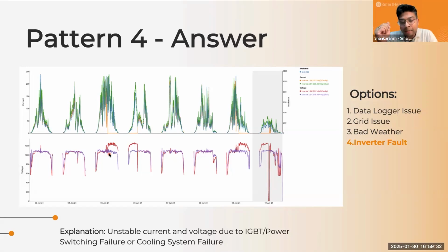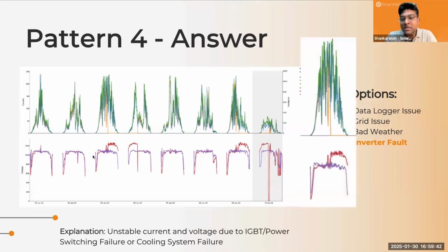It shuts down. A couple of things are extremely important here. First, in bad weather, inverters shutting down could be because of very low irradiance. But if I'm able to build correlations with other inverters having the same configuration, and establish that other inverters are working and this is not, that's the first red flag for me. It's a very common phenomenon for inverters to shut down in really bad weather or low irradiance conditions, so such conditions can go unnoticed. Or as an asset manager, I might not bother myself as much, given that the weather is already bad, unless I knew that this is a pattern.